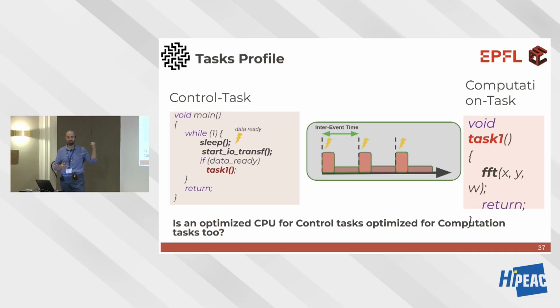So it happens quite often that you use the other CPU for this kind of task. It's completely normal, it's not a mistake. It's just that you have a single CPU that needs to be good in the most critical part of the design. So of course it will be over-designed for the simpler tasks, and here clock gating and power gating come to help mitigate the overheads.